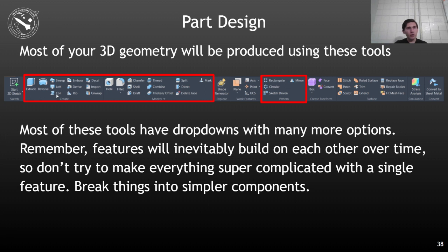There's also the coil option, which, think of it like if you're trying to make the fancy 3D model for a screw, you've got a thread that you can imagine like a little triangle section that you're swirling around a bunch of times around a cylinder. Coil tool is for that. You can also use it to make springs and stuff.